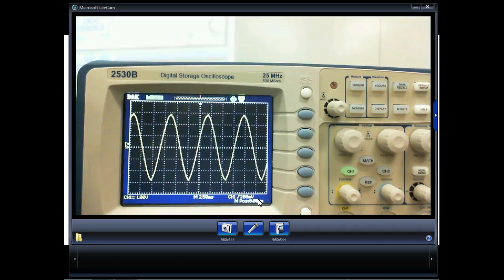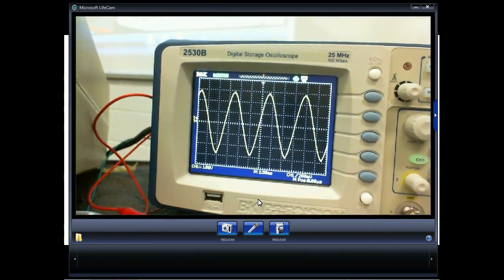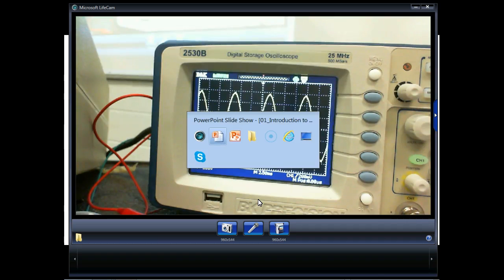This is what's nice about an oscilloscope, folks. A meter averages everything. An oscilloscope shows you what's there. So this is exactly what's there. If I looked at this with a meter, the meter's going to average this out, right? You understand that? And we'll talk about that in a minute.